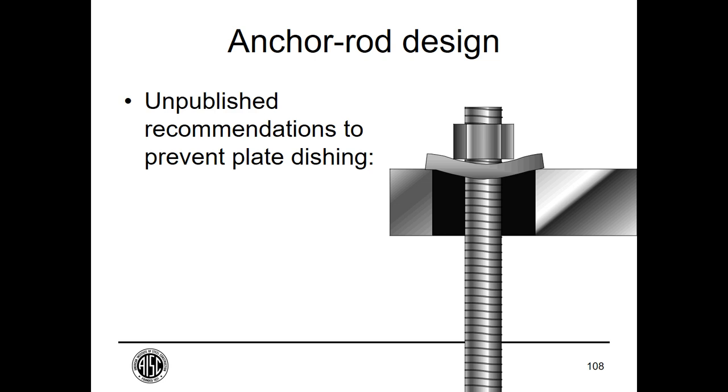I will say that this recommendation is one that I've given before. I've discussed it with various people in AISC and elsewhere, but there doesn't seem to be any publication of test results that we can point to. Nevertheless, it seems prudent to consider the grade of the anchor rod in sizing this plate.